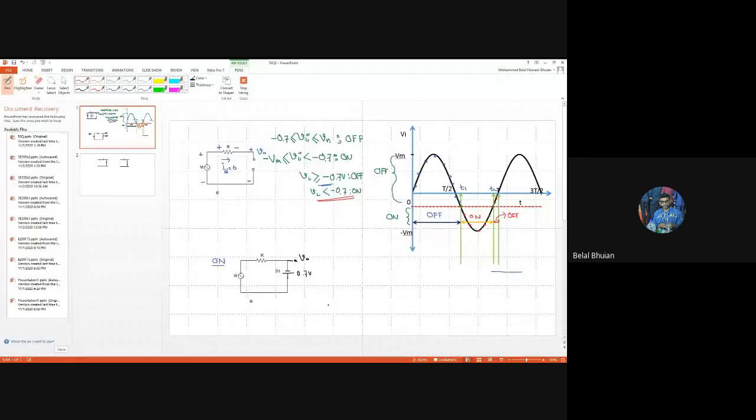Remember in DC circuit analysis, if you want to determine any terminal voltage, what is the rule? We apply a KVL starting from ground all the way to the point, passing through all the elements. So if I consider this ground, I pass through VI, pass through R, and then reach V naught. Yes, you can find it. V naught is equal to VI minus IR. That's one thing. Another way, a shortcut? Can't you see another shortcut way?